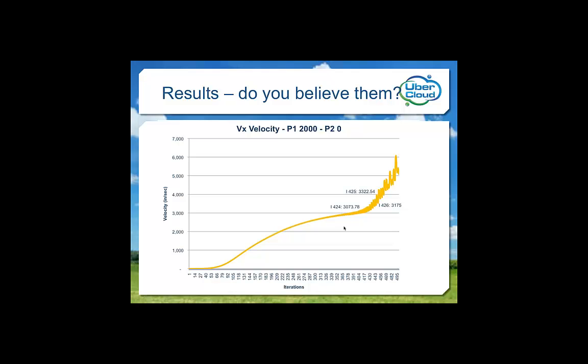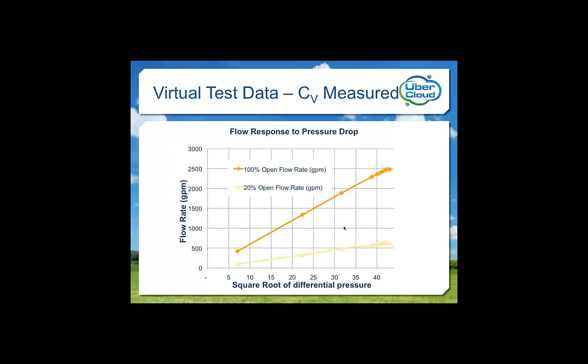The complete data set for each iteration is easily extracted into a CSV file, and this chart was the result. It seemed to me that there must be a group of settings that would allow the simulation to get close to converging and stop before it starts to wander off. After posting this on my team's website, Autodesk politely suggested that I increase the number of layers of mesh at the boundaries of the flow path and make a few changes to the solution settings. Now I was ready to go to the cloud.